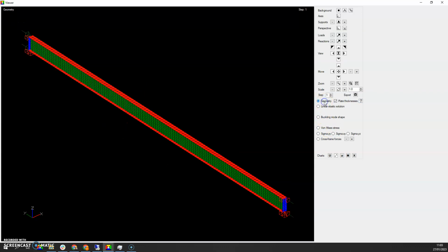And by the way, let's look at the boundary conditions here. You can see I'm restraining all these displacements. Here on that end, it is free to move. I am applying a uniform compression on the column. You can see the green arrows, which are showing the loads. So this column is under pure compression.